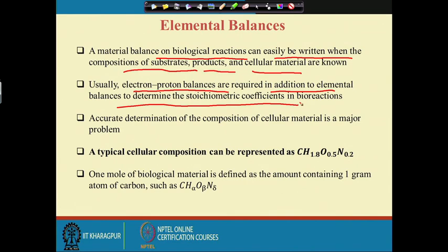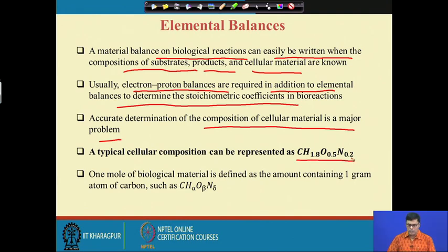This is very interesting. Accurate determination of the cellular composition is the major problem. So, what we usually do is assume a cellular composition of the biomass: CH1.8O1.05N0.2.